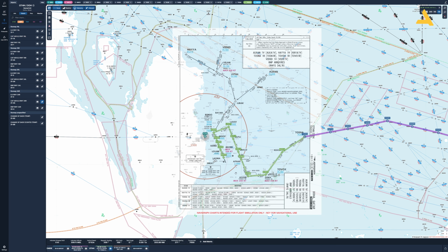Now the arrival actually transitions into approach. So that's why you have a transition point. And you can see Legma. Because this is the runway, 34 right. I will be landing over here. And once I'm at this point, Muxt, my altitude should be between 3,500 and 2,500. And you can see it's written over here that for runway 34 right, expect 2,500. So if I'm going to land at 34 right, I should be at 2,500 because I'm expecting that from ATC.